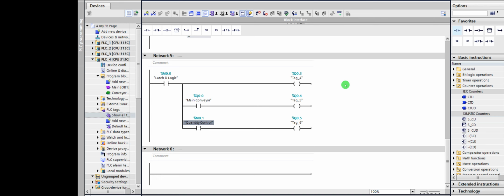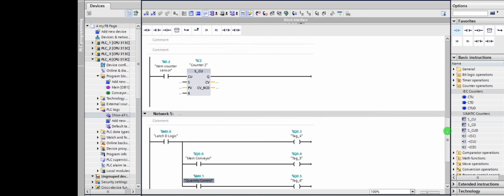Then if you have an issue with the conveyor, if the conveyor is not coming up, you can easily go to the FC block that's responsible for the conveyor. I'm talking about where you have a complex logic, where each logic will contain like 4 networks in one. Then another sequence will continue from another network, containing another 3 networks again. In that case, segment them by block so that troubleshooting is made easy. All right, so if that is carried out, let's now simulate.